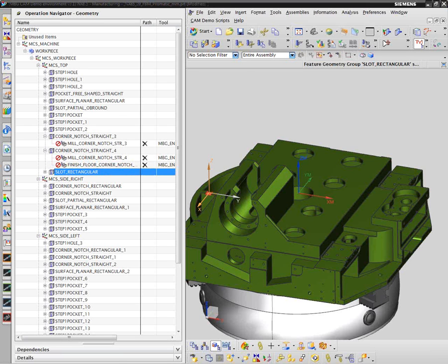Now we've seen how easily, with the use of feature recognition options and machining knowledge, NX is capable of handling different feature types in different directions. It also takes care of PMI information with just a few clicks. We're using established strategies and tools from the library. Now, once we've created the NC operations, NX also offers the option to optimize the sequencing of the operations, and we can see how we can do this on some of the different program groups.